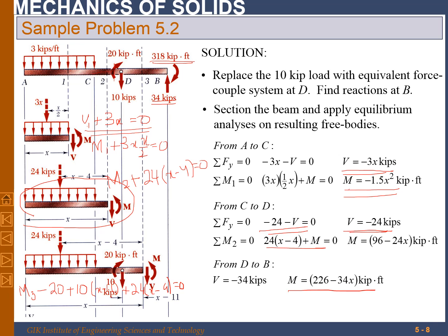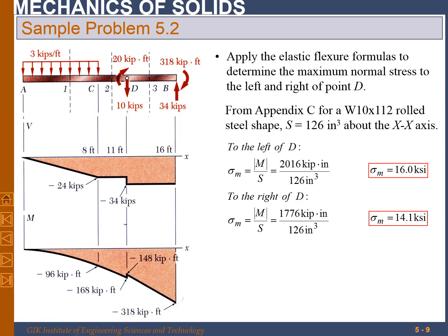This expression is valid from B to D, and this expression is valid from C to D, whereas this expression is valid from A to C. Now it's better to write in terms of x, because again, for deflection of the beam, we need this moment in terms of x. Now, by putting the value of x, we can draw the shear force diagram.